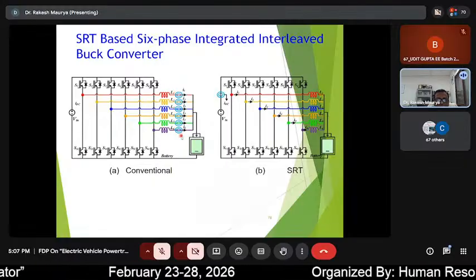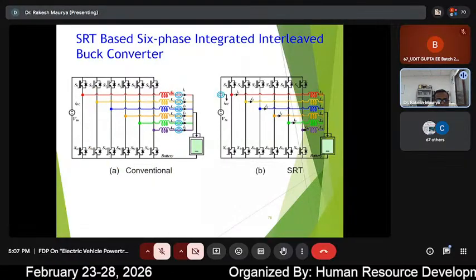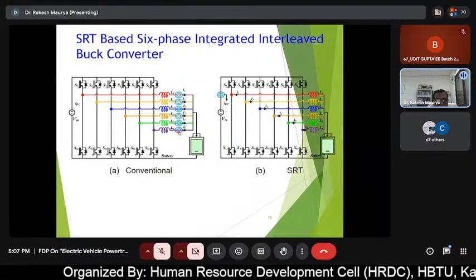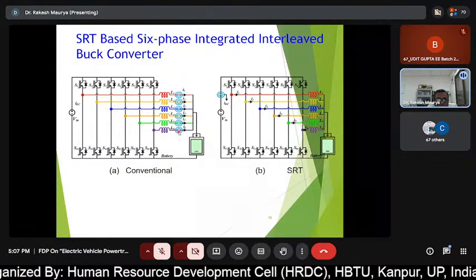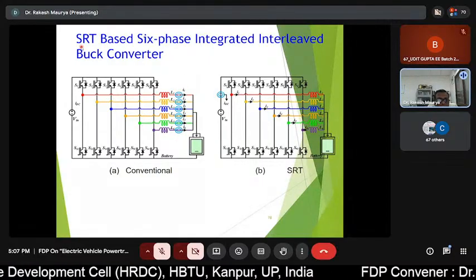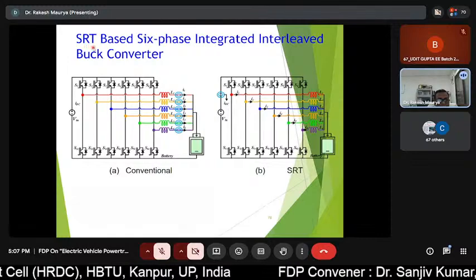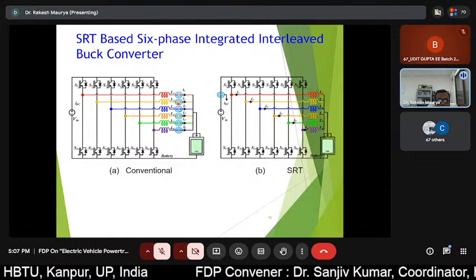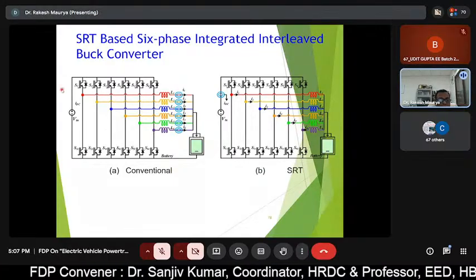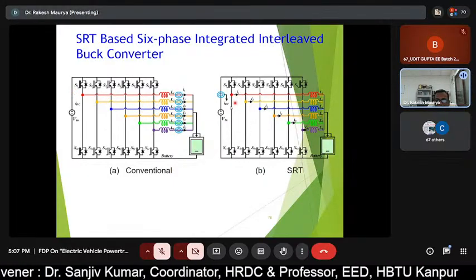As there are 6 phases, to control the machine you require 6 sensors. Again, it's bulky and it's a costly affair. So can we apply some sensor reduction technique? We can remove all these motor winding sensors,